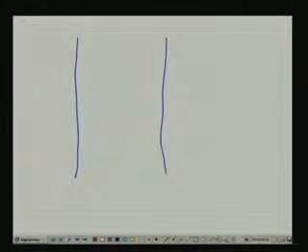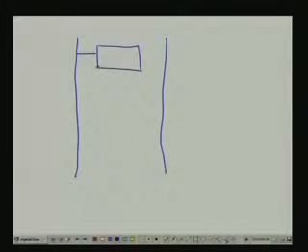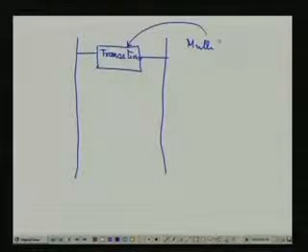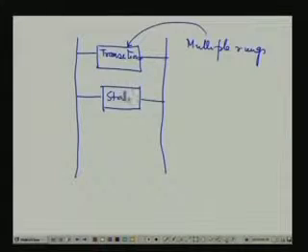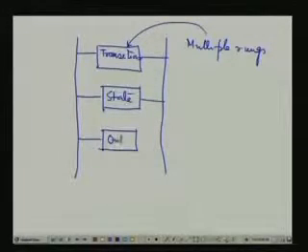So we will organize our program into 3 different blocks. The relay ladder logic will consist of 3 different blocks. The first block will contain the transitions. This is multiple rungs. Then the state block and finally the output block. So we will now describe these 3 blocks in the case of this example.